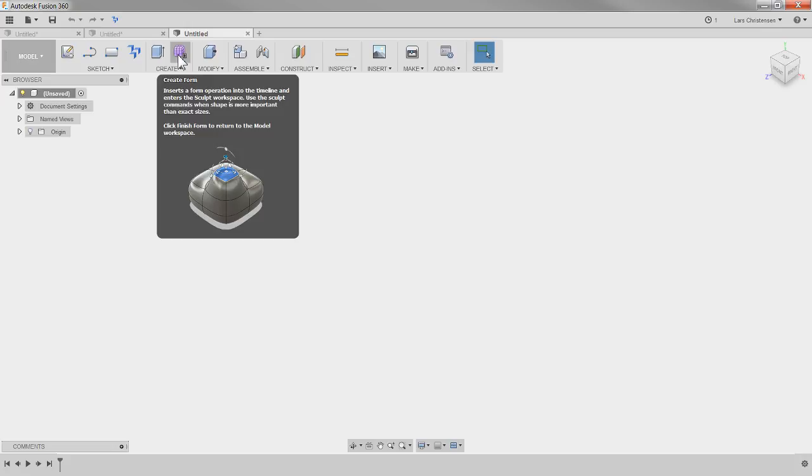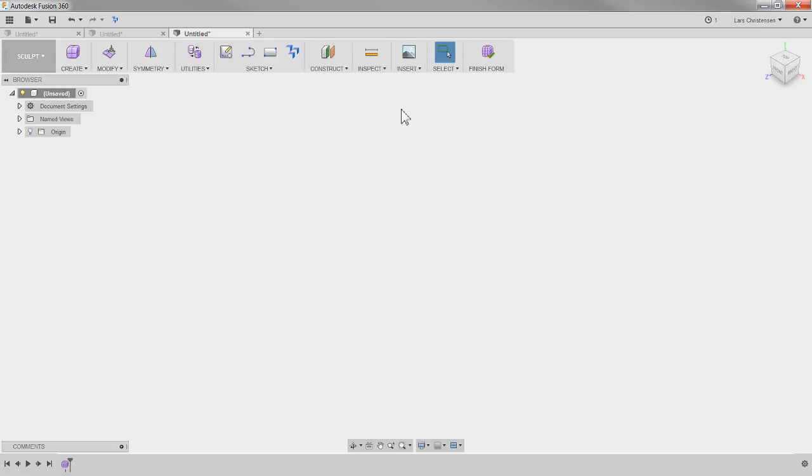We got that whole Sculpt workspace inside of Fusion where we can pull and drag and create these different shapes. However, when we're done with things inside of the Sculpt environment, if we don't completely close it and make it watertight, that will also become a surface body. So let me show you that. I hope this is not confusing, but that's always my fear, right?